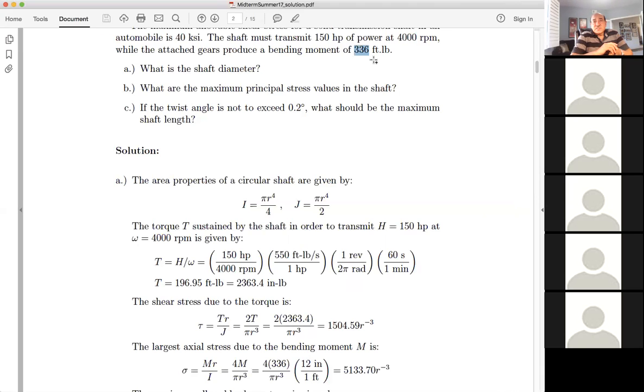And the maximum shear stress, as we know from Mohr circle, is not the actual shear. We have to rotate the angle until we find a situation that we have pure shear, or pure shear and some tension compression, which is the radius of the Mohr circle. And the radius of the Mohr circle is the maximum shear. So the failure criterion is based on the maximum shear.